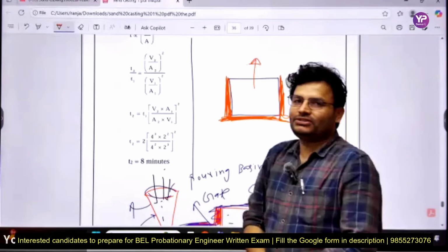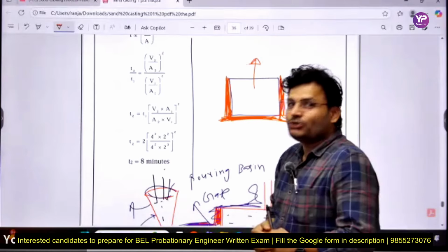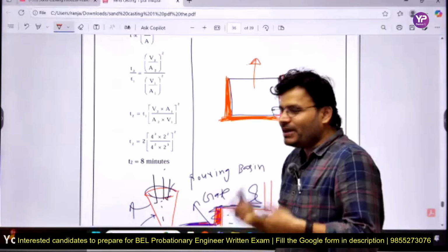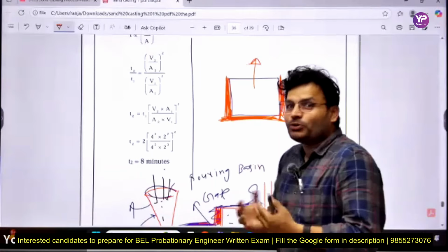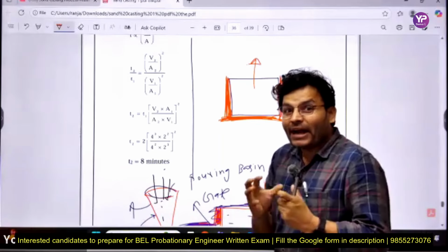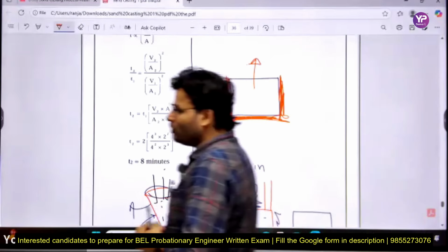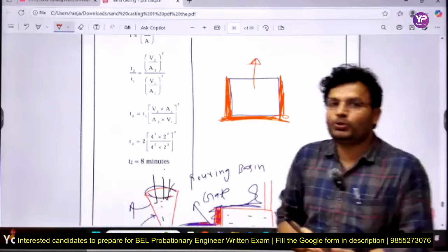Now see my dear friends, once you take out that pattern, can you say there will be an effect on the sand? Obviously, sir. Sand may be distorted, sand may erode. In all those cases, your product will be very, very bad. And that's why you need the pattern allowances. Pattern allowances are provided so that any problem that is there can be overcome.